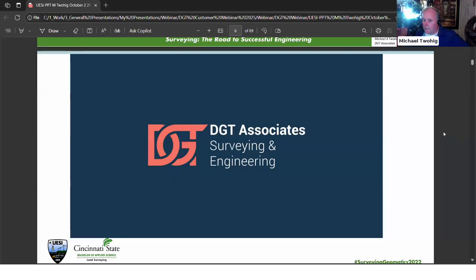I literally have worked with mobile LiDAR collection, and you can imagine that, say on Vassar Street, there were 2 lanes in each direction. There's parking lanes, and there's also bike lanes that we collected in. So we're doing 6, 8, 10 passes on a single street with a GPR to get the coverage, because it's directly below the antenna. When you go up and down the street with a LiDAR, you may need 2 passes to collect the data. But if you're collecting it 8 times, that's absolutely a waste of time. So we don't feel that the 2 systems work great together.